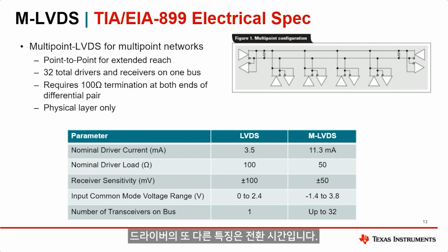Another feature of the driver is the transition times. The transition times are limited to a minimum of 1 nanosecond, which comes into play when you have transmission line stubs. I'll talk about that a little bit more in the design considerations portion.